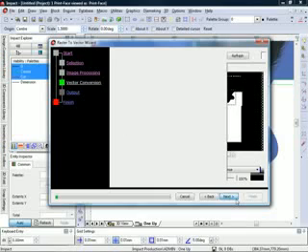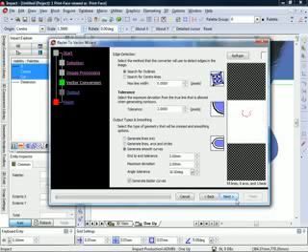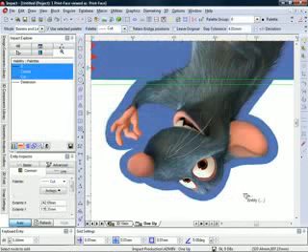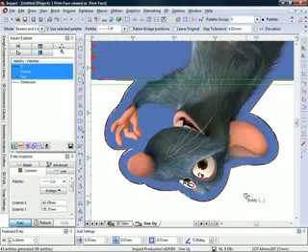The Art Trace wizard will use default settings to create a series of lines and arcs around the defined area, after which the user can fine-tune or rerun the feature if required. Once the Art Trace wizard is closed, the geometry created will appear in position on top of the artwork. At this point, I'm going to turn off the graphics visibility to allow me to tidy the geometry.